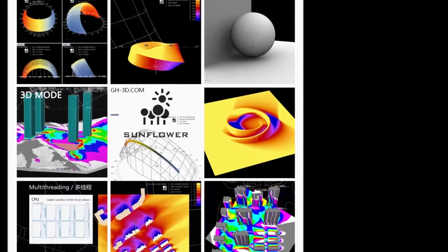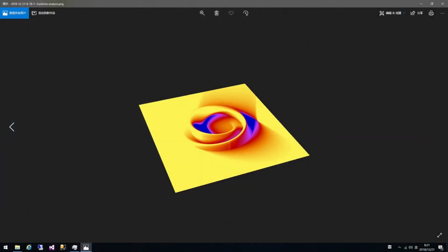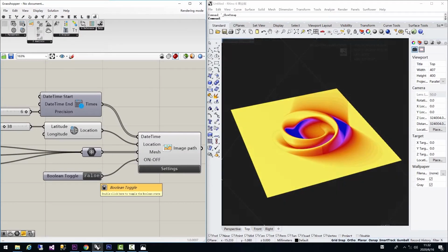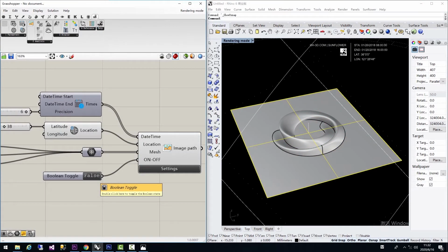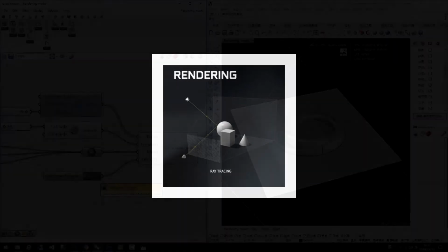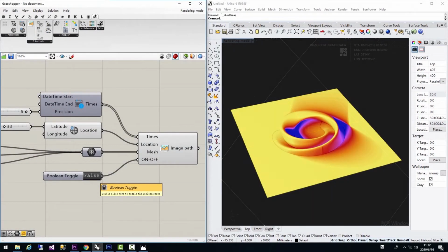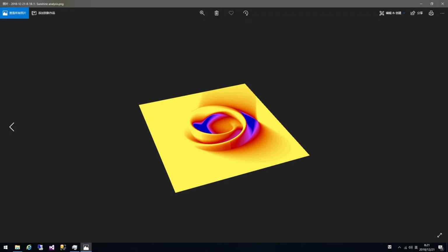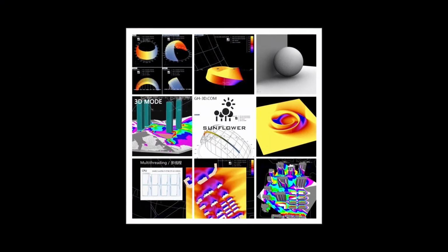The fifth way is a rendering mode analysis. It gives us a very fine and smooth sunlight analysis result. The precision and resolution are determined by the display resolution of your screen, but have nothing to do with the subdivision of your mesh. The algorithm will capture the sunlight exposure of every pixel of your active window and quickly render them out as a sunlight analysis image.